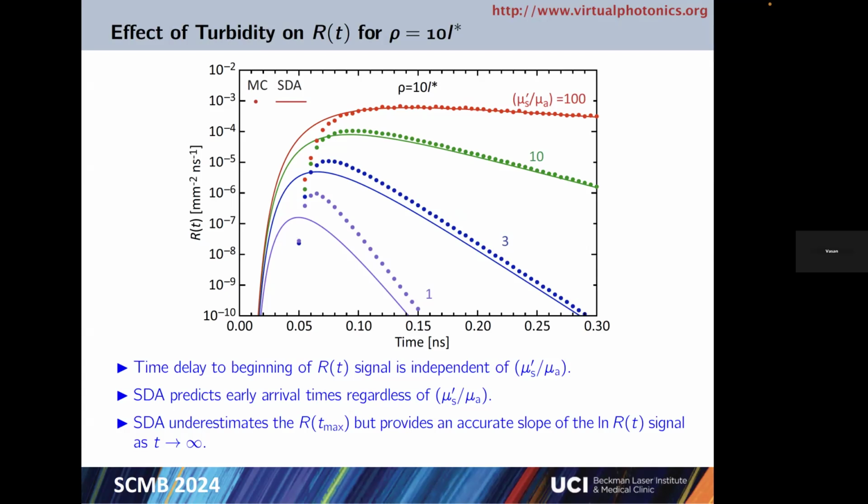These signals are so clean. In reality, your actual measured signal is dispersed in time, and they can also have humps in it, because PMTs are notorious for having this ringing after pulse. And so often you have a single rise, and then you have a secondary rise due to this after pulse, and that can really compromise in a massive way your ability to separate absorption and scattering. So we're kind of sweeping all of that under the rug in this context.